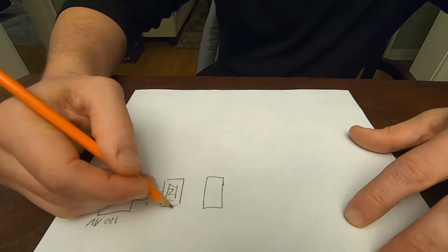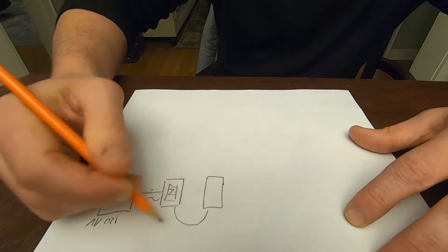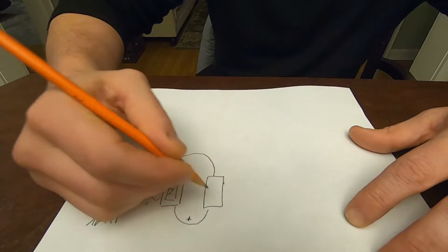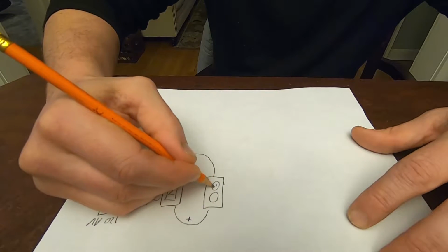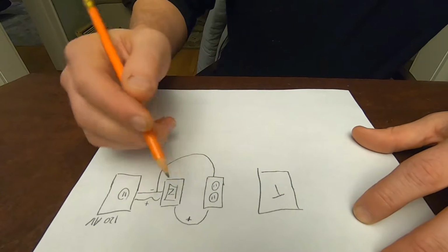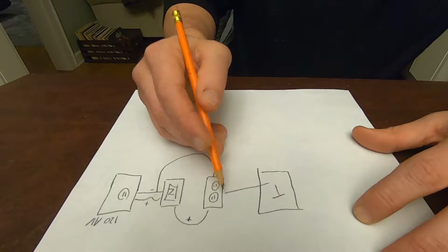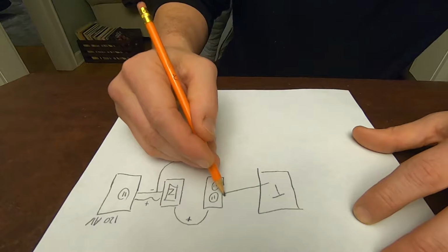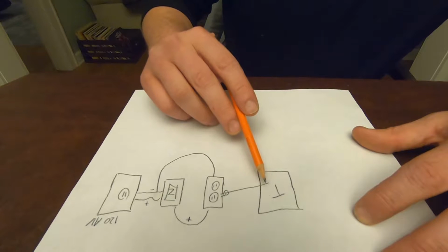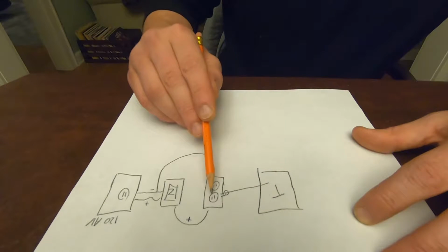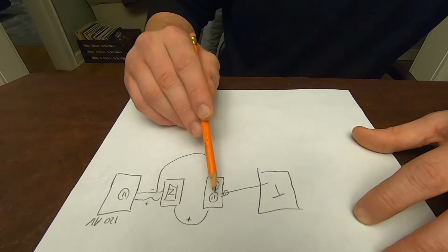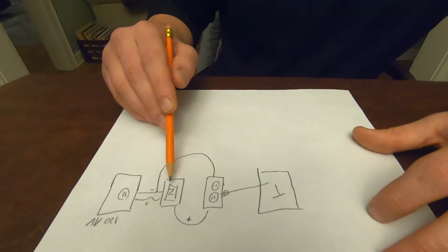And from the Z-wave output, the load line, which is the positive, the ground is going to go straight over to our single gang outlet. And then from there, the transformer is going to plug into this outlet with its standard connector, right? Standard AC plug, wall plug, USA style. So now the transformer is actually plugged into not a 110 or 120 volt outlet. It's plugged into an outlet that's being controlled load-wise by the Z-wave dimmer.